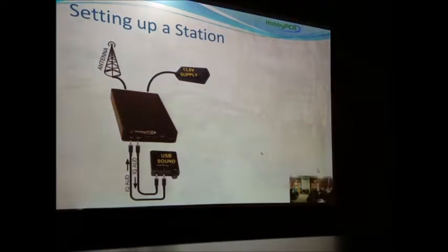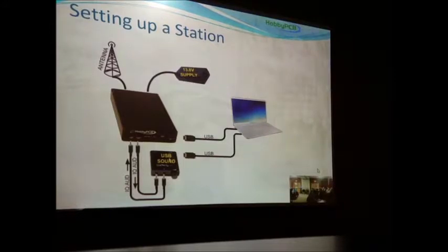And we're gonna have to hook up both the radio and the sound card to the computer with USB. Now, of course, the sound card has the data stream that carries the RF data that the computer is going to decode. And the second USB goes to the radio to tell it what frequency to be on and then tell it when to switch from transmit to receive. Now, at this point, you can actually probably do some operating as long as it doesn't involve talking to anybody. This would be good for digital modes. You could use PSK31, FT8, Whisper, with software just running on the computer.